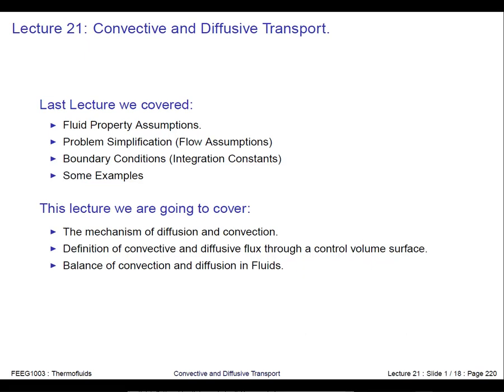Okay, so this is where we start looking at fluid dynamics properly, and fluids are quite interesting because they can move information through a fluid by the mechanisms of diffusion and convection. So we kind of know about diffusion, which is molecular transport of, say, heat through a steel bar, and this happens in a fluid, and convection, where the velocity of the fluid actually moves information. So if you imagine you've got hot fluid and you put it in one end of a pipe, convection of the fluid is moving that energy from one end of the pipe to the other.